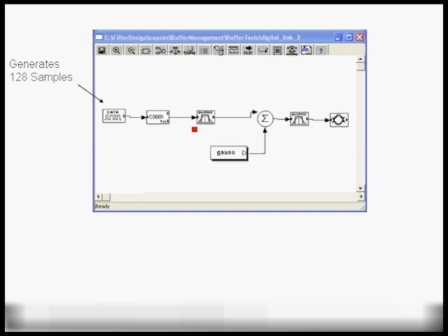In fact, it's very efficient because the filtering block here would consume all those samples on its call and efficiently process them and output them on its buffer. Now the buffers only grow if they need to, because in general, in order to limit the memory footprint, we limit buffer sizes to, for example, 128 segments. We don't go and allocate, for example, 8 times 128 for each buffer. We limit it to 128 samples, but they will grow in order to accommodate multi-rate signal processing.